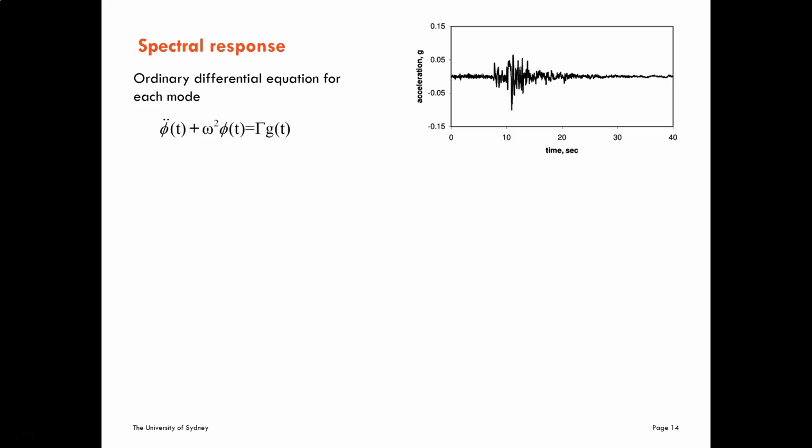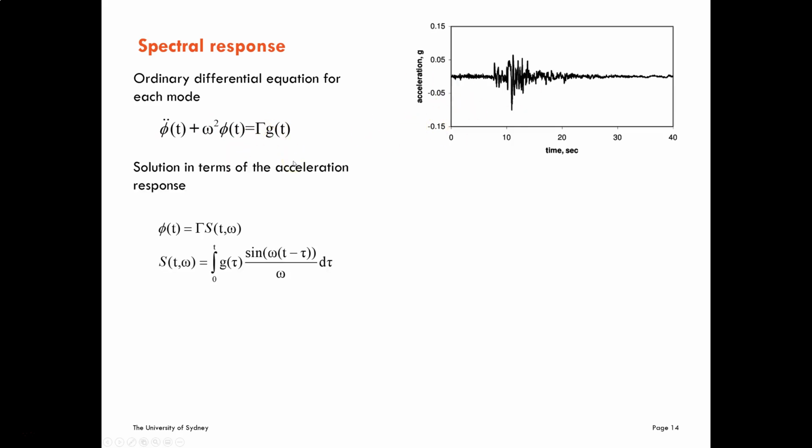So the ordinary differential equation that I have to solve is this one, where this is the ground acceleration. The solution is already given. We solved this already. It is the Duhamel solution that is simplified here because I did not include damping. And I am going to introduce a quantity that is the peak acceleration response. The peak acceleration response is the second derivative of this quantity, and I take the second derivative and calculate the maximal value of the second derivative.